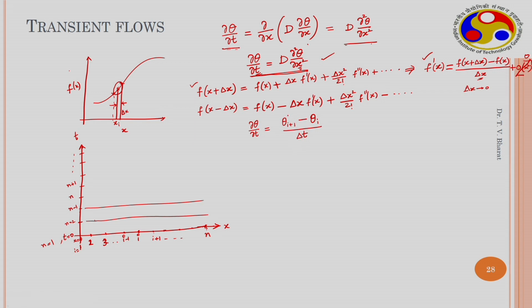So, now I can solve this particular form in the nth level itself. N could be 1 and I could be 1 in this particular case, or I could be 2 in this particular case, because I equal to 1 becomes a boundary condition. What happens at the boundaries? We already know the information. Theta at x equal to 0 is equal to theta s, that information is known. So, this can be approximated to this.